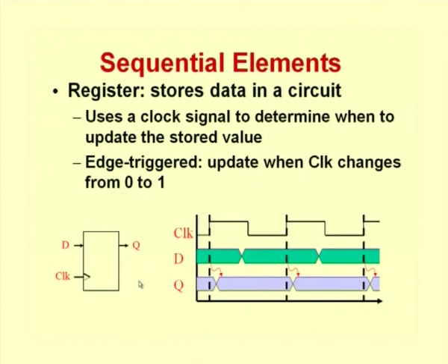So, if I have a D flip flop, when the clock changes from 0 to 1, the value which is there in the D input will go to the output Q. So, you can see what is happening here. Even if the D value changes in between, until the clock input changes from low to high, you can see that the output Q will remain at the same value. Whatever value D had here, that value will be stored inside and available at the output here. Only when the next clock occurs will this change be reflected. You can see the same thing happening here. This is something we already know, just to brush up this important concept.